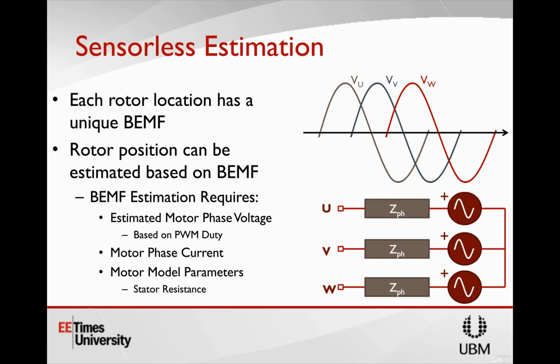Because effectively, that back EMF actually tries to counteract the voltage we're applying to this phase. So the more voltage we apply to the phase, let me restate that. The faster we try and spin the motor, the more voltage we need to apply to that phase in order to overcome this back EMF, because this is resisting our rotation.